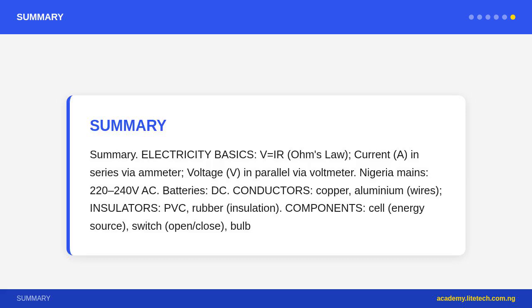capacitor, diode, LED, transformer. Wire colors: brown equals live, blue equals neutral, green/yellow equals earth. Safety: switch off before working, correct fuse rating, secure connections, earth metal-cased appliances, test dead before touching. Multimeter measures V, A, Ω: voltmeter equals parallel, ammeter equals series, ohmmeter equals circuit off.